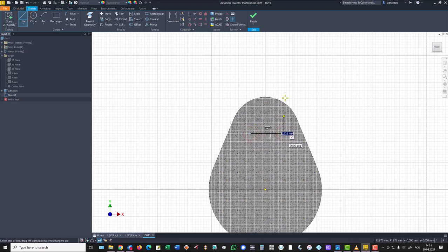This is a horizontal. We keep pressed the left button of the mouse and we go here, then back to the bottom line. You see we have here 2 constraints and Inventor waits for us to place 6 dimensions. Take a look. We place this point on the same vertical with this point. Now we have 5 dimensions.